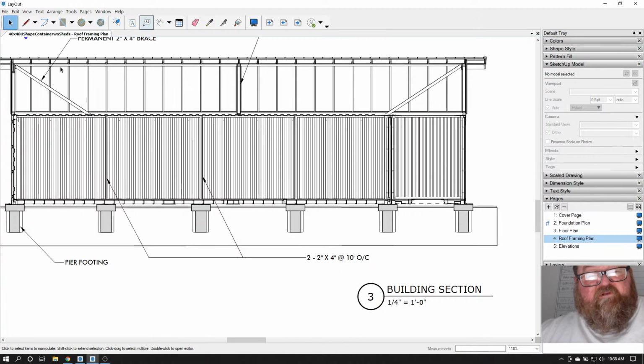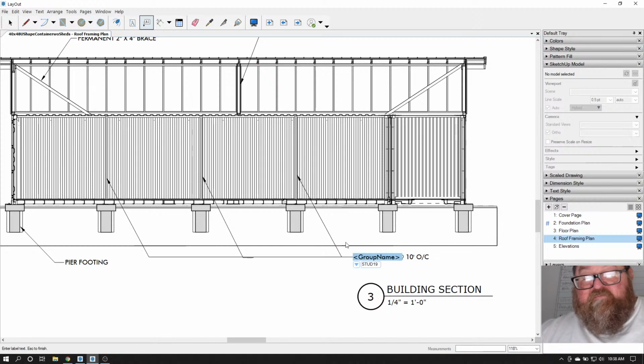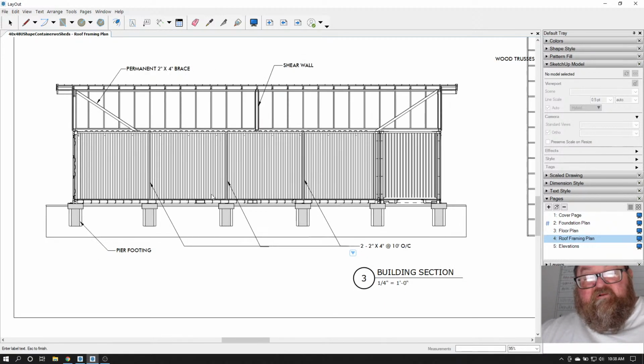This is going to be weird, I know, but I want this to be very obvious, because I don't want them setting this 5,000 pound per linear foot roof on top of a shipping container that supports 300 pounds per linear foot without these 3 double studded posts in here at least. And you see they're lined up with studs here.